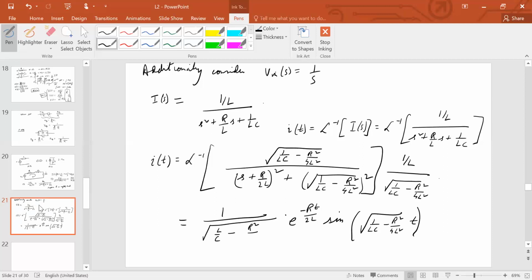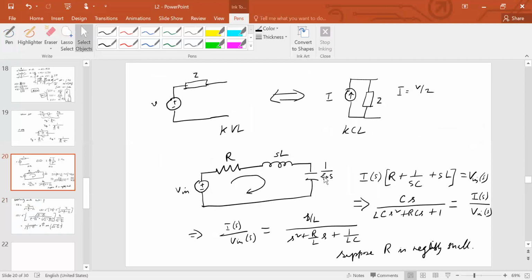So that's because physically you can see that the capacitor, the charge builds up across the capacitance, and once the entire charge has built up, this capacitor will behave like an open circuit. Yeah, that's what happens at steady state with capacitances. Capacitances behave as open circuits, inductors behave as short circuits.